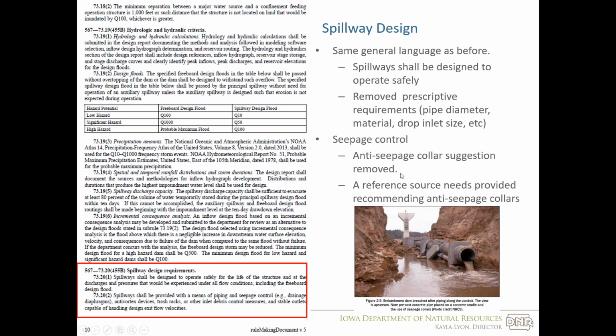Seepage control, we removed the wording that suggests anti-seepage collars. That doesn't mean they're not allowed. It just means we're not suggesting them on a small dam. If you can find a source that recommends them for the size of dam that you're designing in hazard classification, we would review that. And here's the nice picture of seepage collars in action.